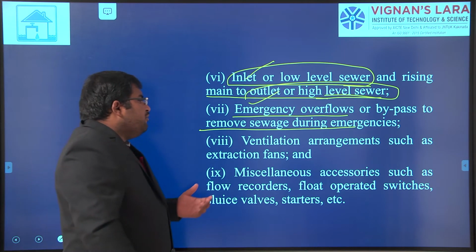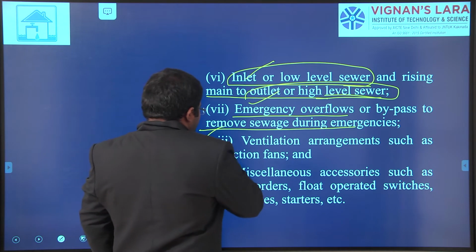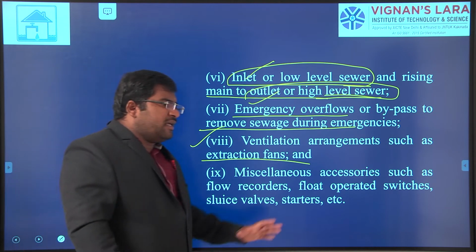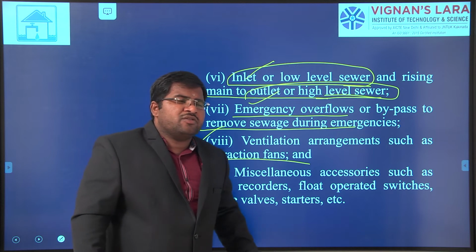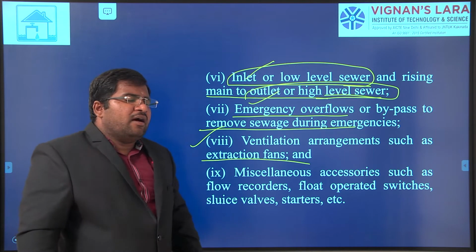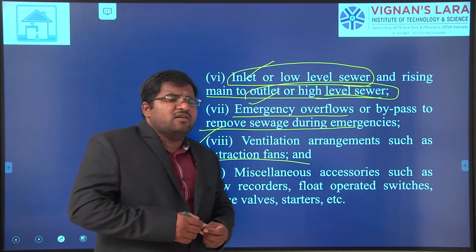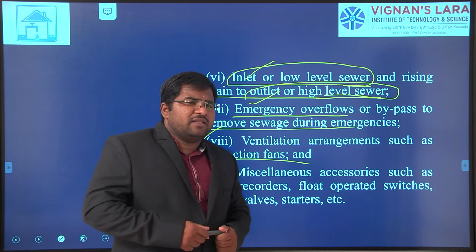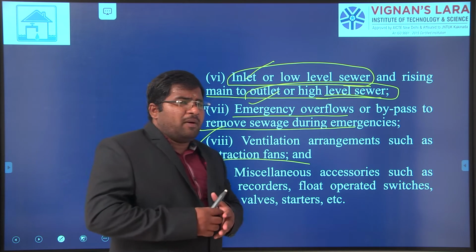Next, ventilation arrangements such as extraction fans need to be there. If you keep the sewage there for many days, it is going to putrefy or biodegrade, and it is going to create many gases. With that, you will get odor, so workers cannot work properly. That's why we have to create ventilation arrangements in the pumping station.